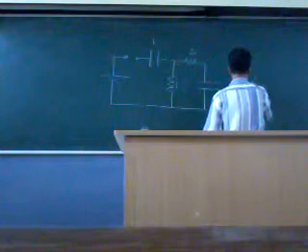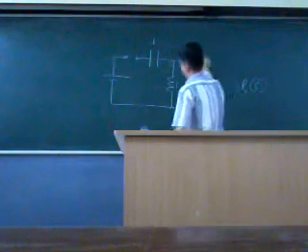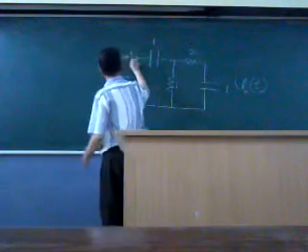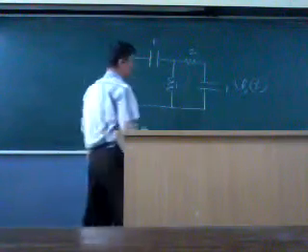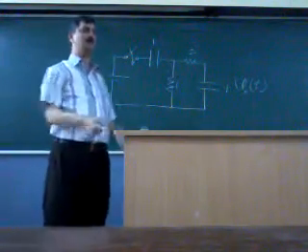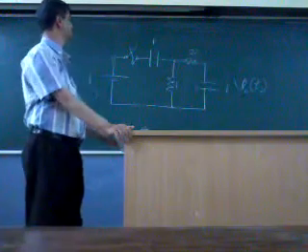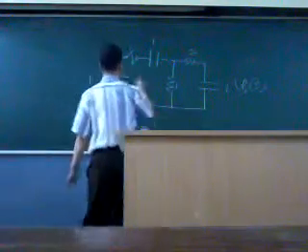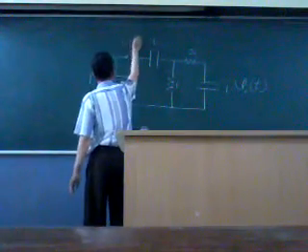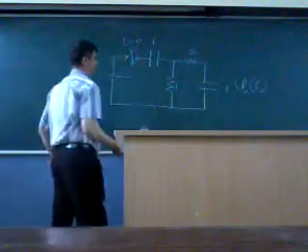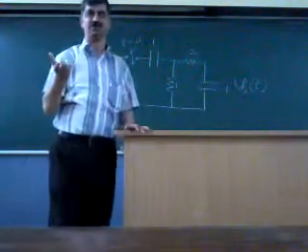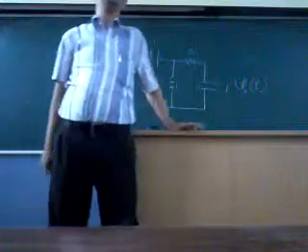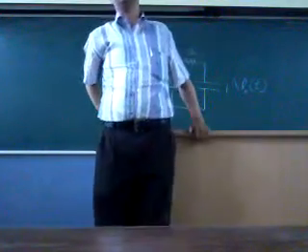And the question is, find out V0(t). This is the formula. This is obviously the same one. Find out V0(t). If the switch is closed at t equal to 0, both capacitors are uncharged. Both capacitors do not possess any charge across them. So voltage across both capacitors is 0.